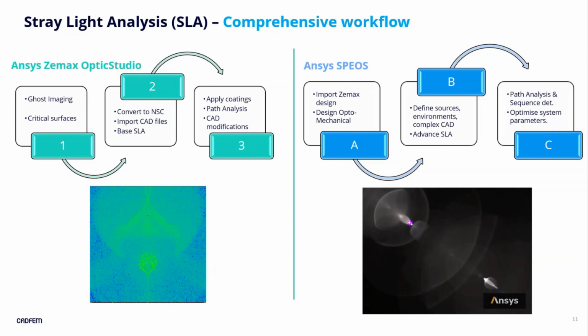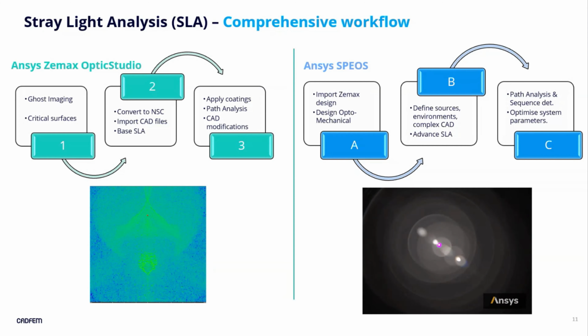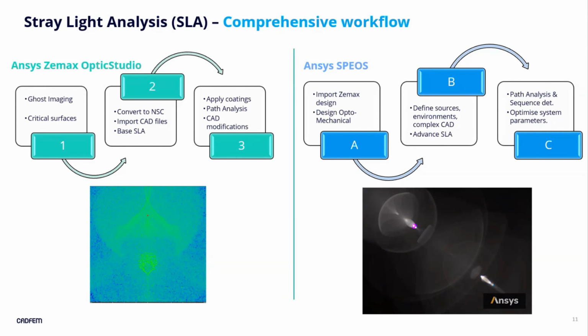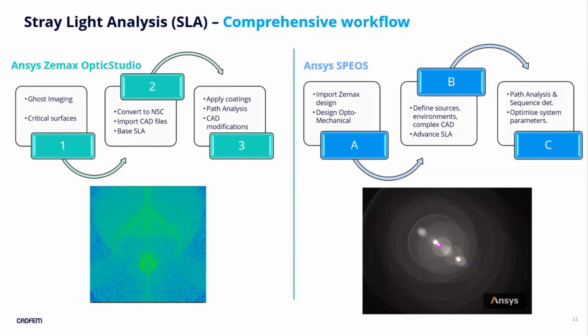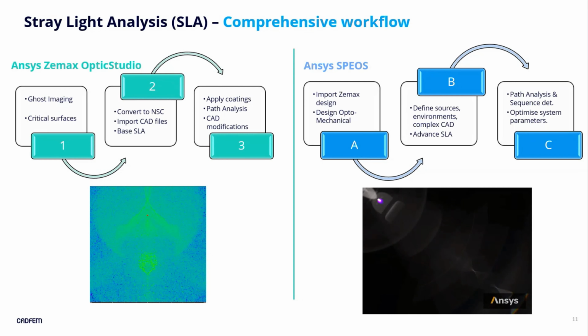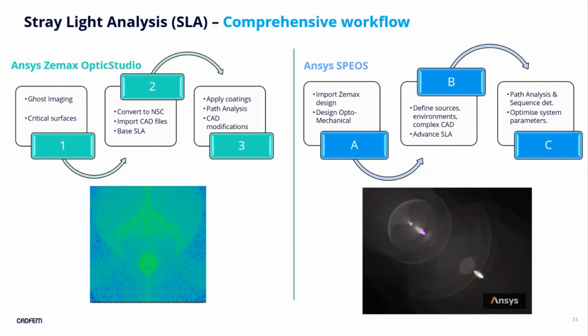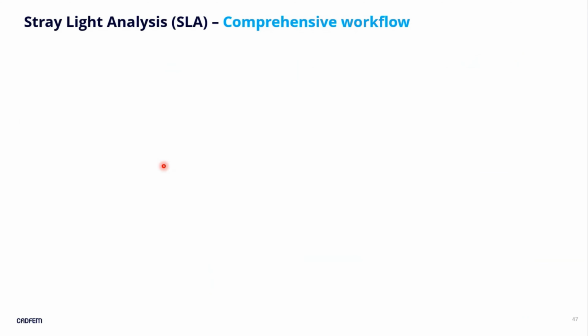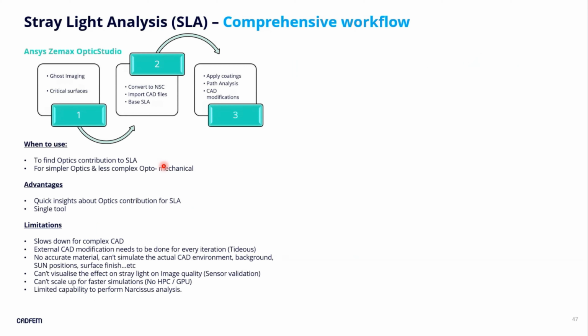Speos is a CAD agnostic platform, so over there you can do the opto-mechanical design. Then you can define the sources, environments, and complex CAD, and perform advanced stray light analysis like sensor validation, non-sequential path analysis, as well as baffle optimization.